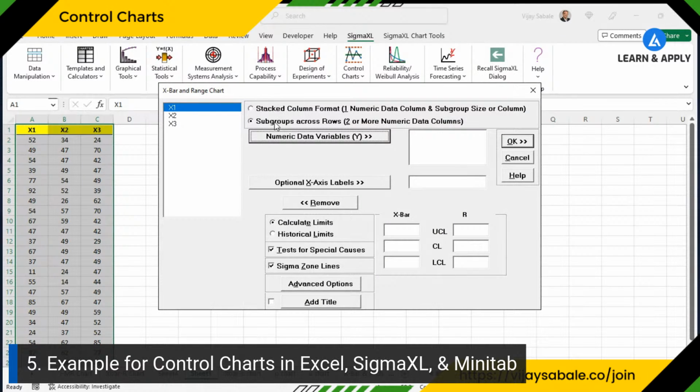Here again, there are two options. Stacked column format, where there is one numeric data column and we have some subgroup size, or we have the subgroups across the rows. So similar to Minitab, we need to select this option, subgroups across rows, the second one. And for numeric data variables, we need to select all these three columns. As we are going to calculate the limits, keep the default selection as it is. Or in case you are going to use this for monitoring purposes, we can use the historical limits.